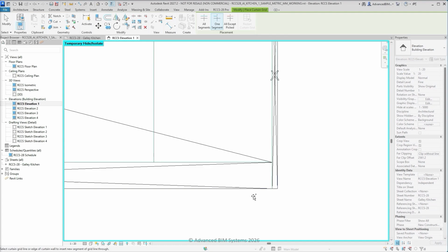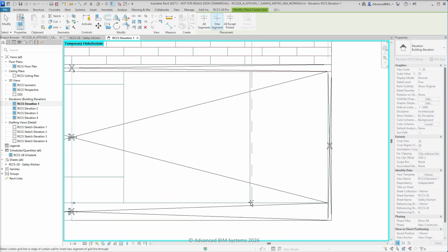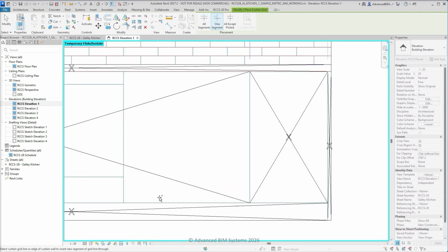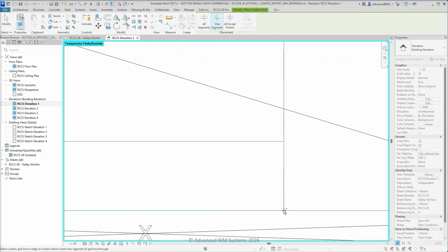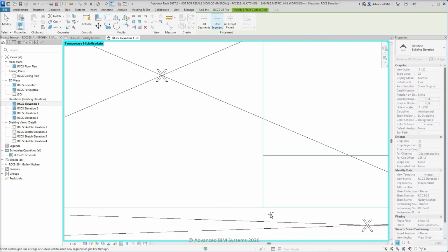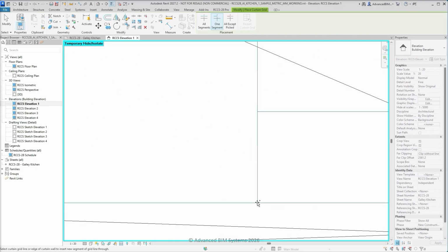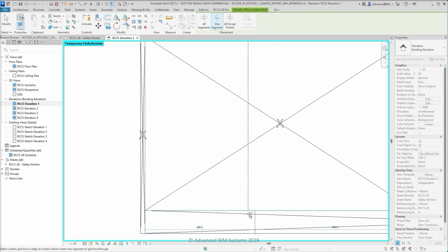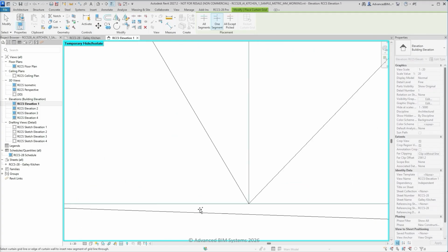The grid tool will almost always automatically and accurately snap the grid onto a reference sketch line. This grid snapping will occasionally fail, but is easy to fix by using the Align tool to correctly locate the grid onto the reference line.